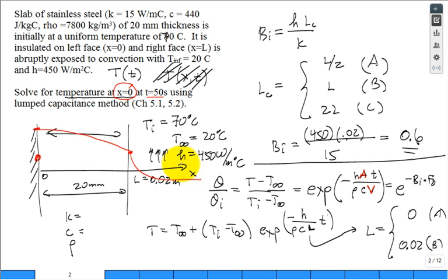And so the lumped capacitance method is going to give you a pretty good approximation of the average temperature in the slab, a single value. The actual value out here at the surface will be lower. The actual value in the center will be higher than the single value temperature that the lumped capacitance method predicts. It's 0.2 that goes in there.